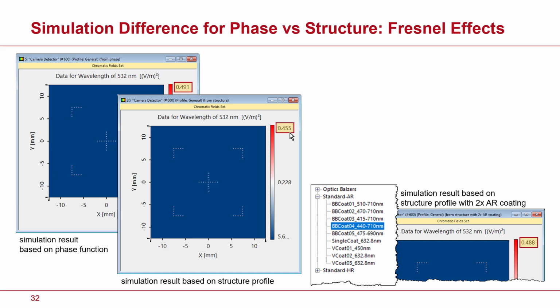So now you can also do certain tests for coatings. Here I apply an anti-reflection coating for our wavelength in the range of 532 nanometers. It's fitting here. And if I simulate again, then we are back in the range of the initial design, the initial simulation result.